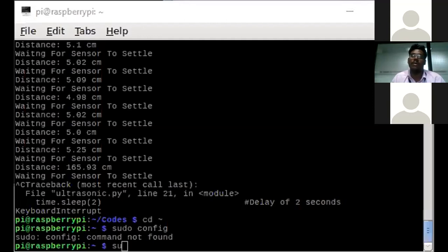Start the position from the camera. Sorry, the display slot. Opposite the display slot, you just start from 1, 2, 3. It has 5V, 3.3V, and also 7 ground pins. So whatever ground you need, you just use it. It can use SPI, I2C, and also UART communication. So whichever communication you want, whatever modules have been connected, you can use whatever you need.